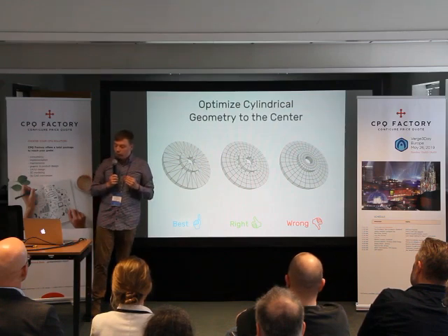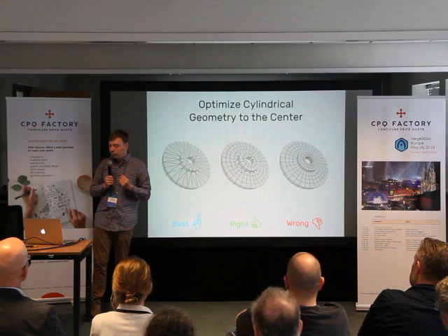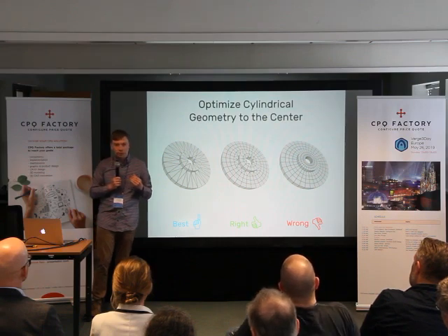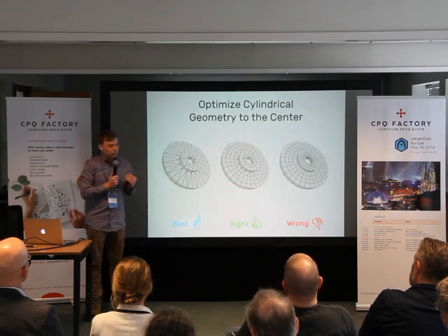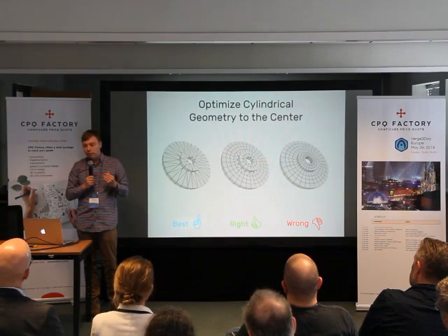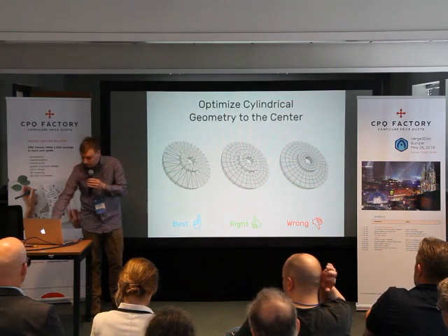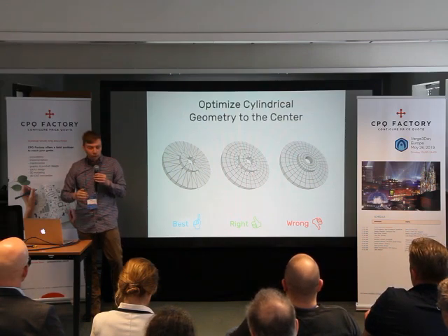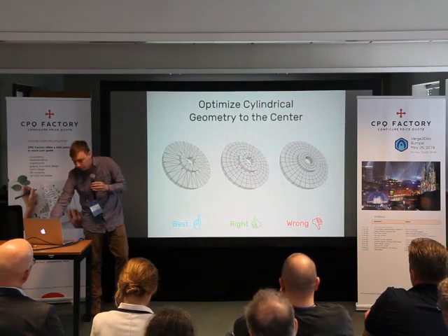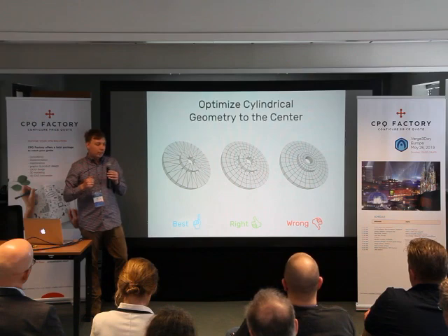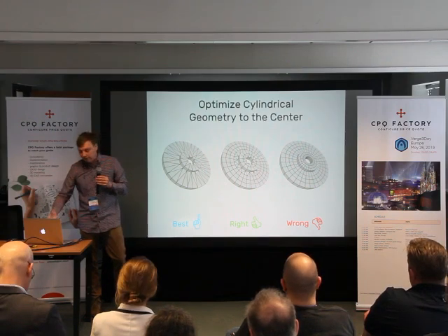When you make a cylindrical object, it usually increases the amount of polygons towards the center of it. So it's better to decrease the amount of polygons in its center by hand to get the most optimized result and to keep the level of detail for this object the same.